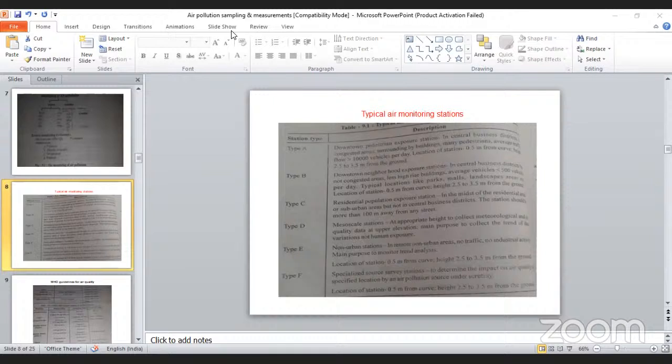So whatever it may be, at the end of the day, you should be having good collection efficiency, and you should retain the stability of the material. And it should not be having any interference with the outside meteorological parameter or anything else. And we have to understand the entire mechanism, whatever we have followed for the sampling and the recovery at last. The first 3 must be 100% efficient. What is the first 3? That is collection efficiency, sample stability, and recovery. It should be 100% efficient.